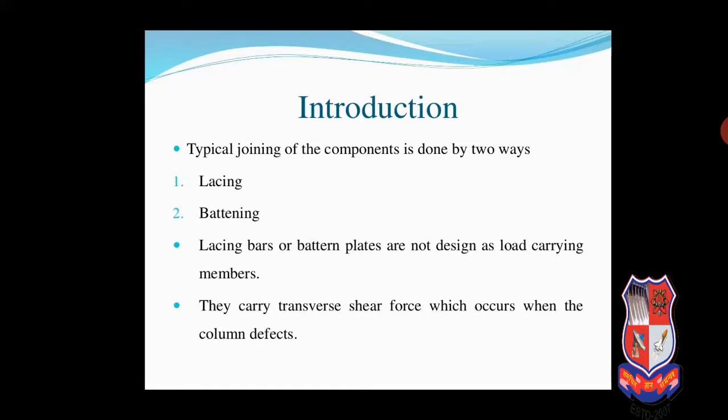Before we start lacing, we should know the function of lacing and battening plates. The function of lacing bars or batten plates is to hold the main components of the built-up section in their respective positions and to resist the stresses in them. They are not designed as load carrying members, but they are designed to resist transverse shear force that occurs due to column action.